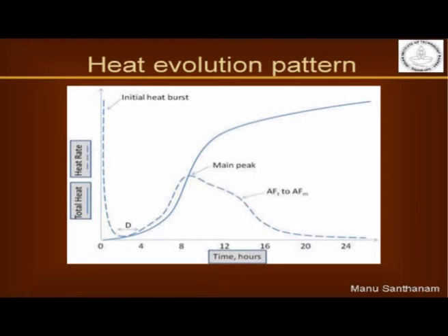That means the reaction is not discontinuing there, it is still continuing, but then you have a very low heat rate, and then you see a sudden rise in the heat rate. After a certain period, let us say 2 to 4 hours, you see a sudden rise in the heat rate, and you culminate in this peak which is named as the main peak of hydration. You see, this is the main peak of the hydration process.